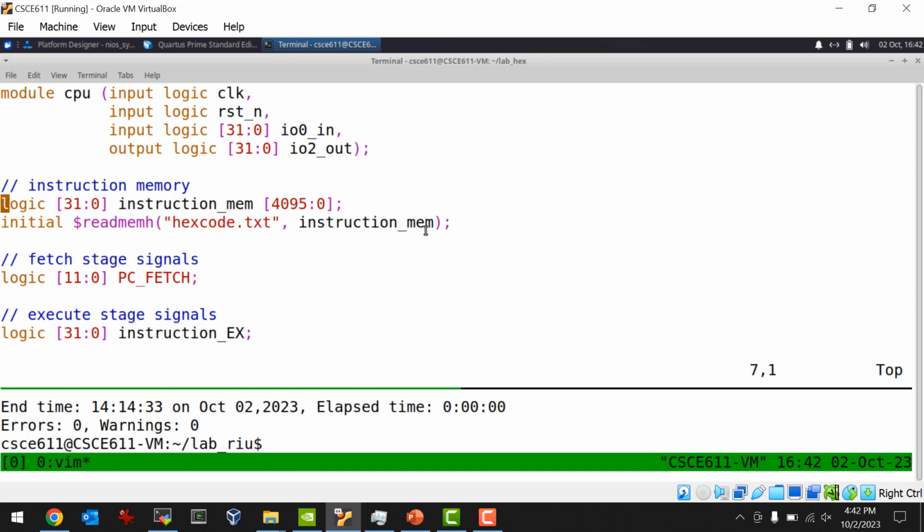the instruction memory, which I declare here. You can make it deeper than this if you want. I usually use 4,096 instructions deep. We have more memory than that, but your programs will be like 100 instructions or so. But if you have 4,096 instructions, then your program counter has to be the log base 2 of that, which is 12 bits, so 11 down to 0.